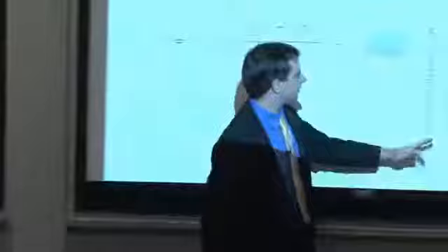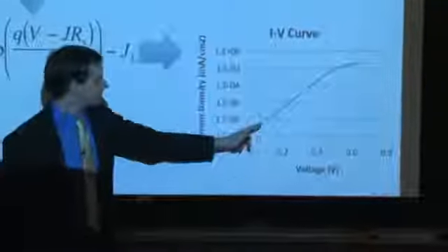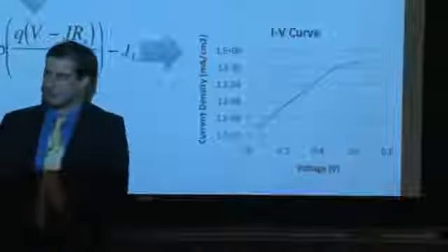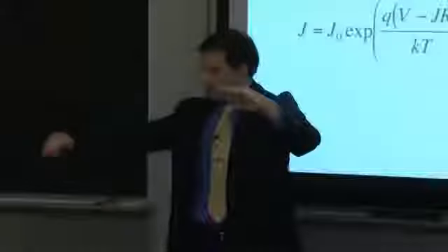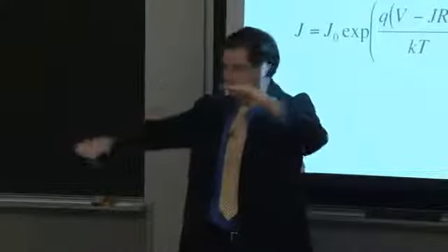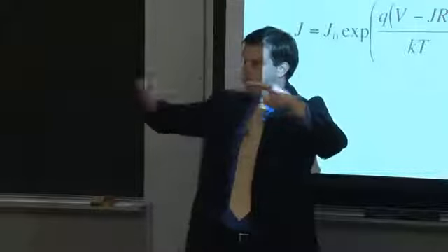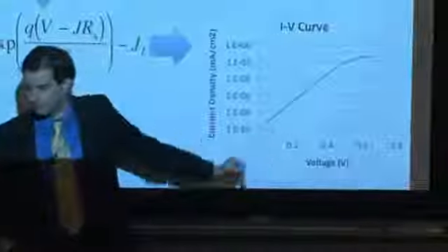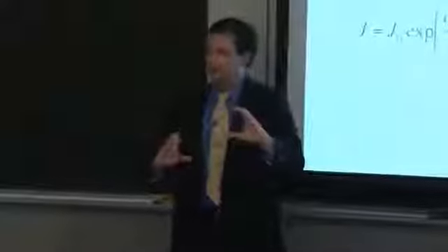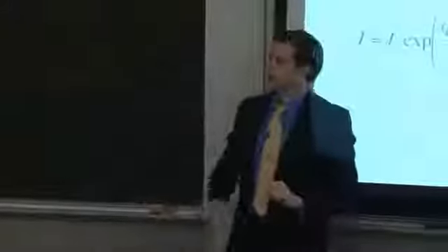So think of this as being a very strong diode, right? In the absence of shunt resistance, you have a very strong diode. You have your p-type region and your n-type region, and that large barrier is preventing the diffusion of electrons back into the device. It's preventing this from rising. It's keeping it low. And that can only happen when the p-n junction barrier is uniform throughout your entire device.